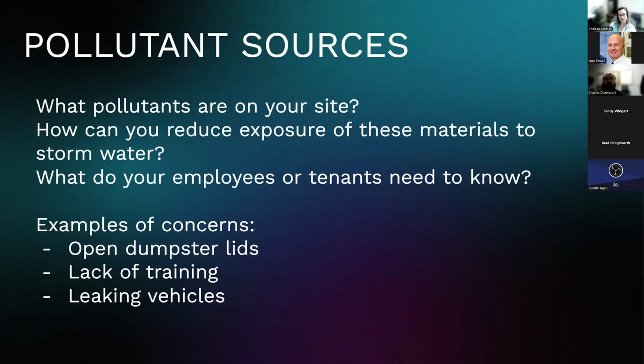Examples of concerns that have been mentioned are open dumpster lids. We don't want stormwater going into that dumpster and then being leaked out because the dumpster plug is missing, when you could just have lids on it and the stormwater would never mix with those pollutants.